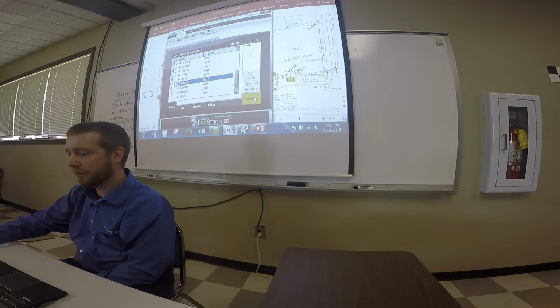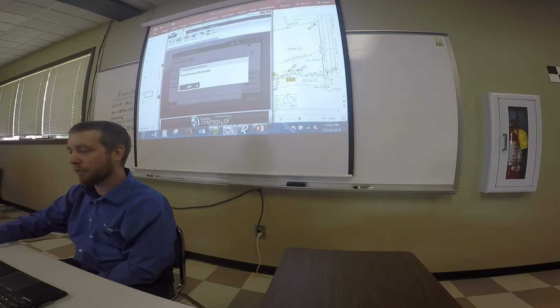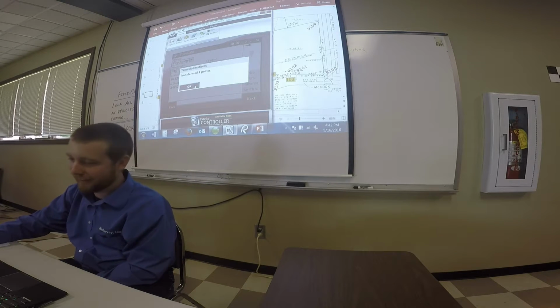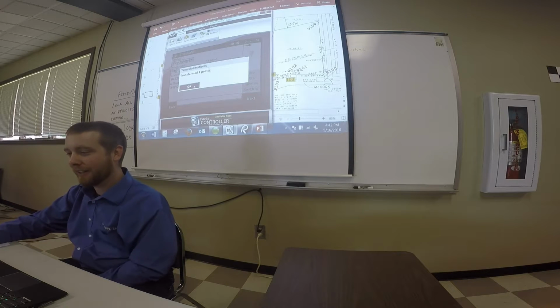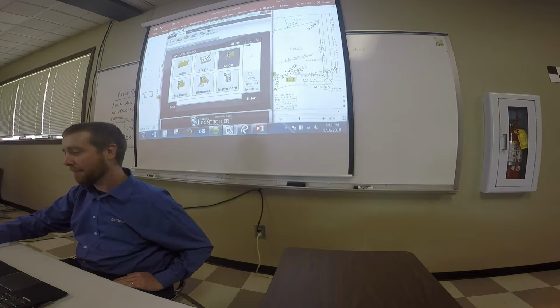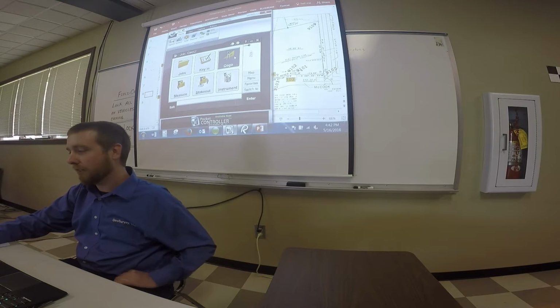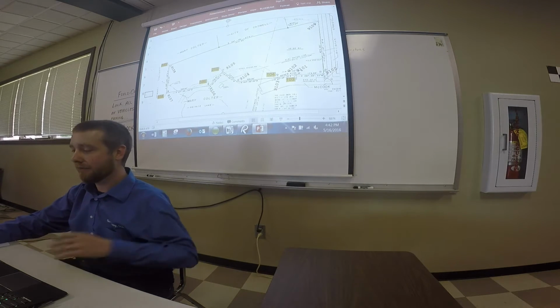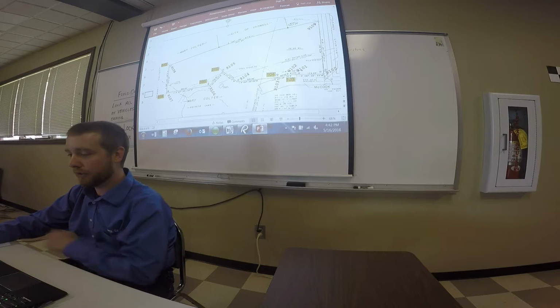We'll hit accept. Transform 9 points. Didn't select that. 9108. It's 9108, but that's fine. Okay, well, we'll remember that. So now, what we've done is we've translated that block of points up to 103.